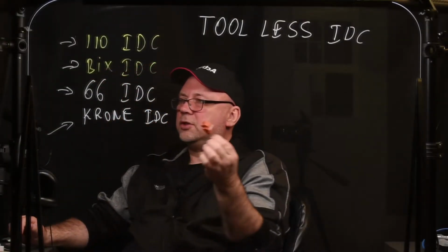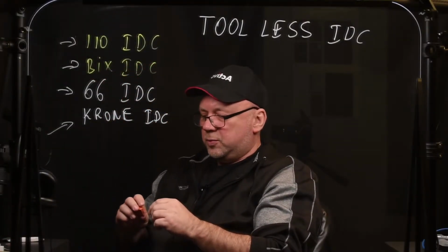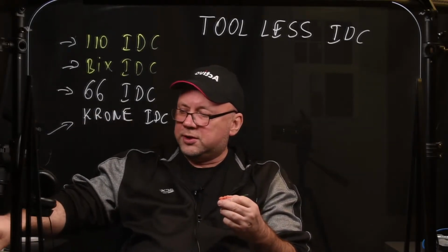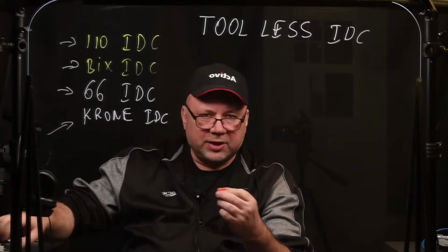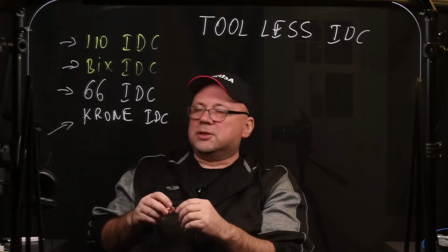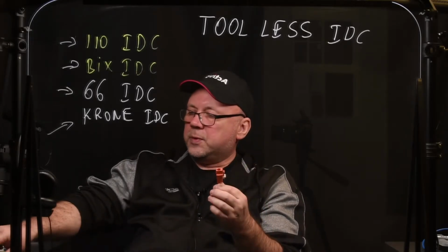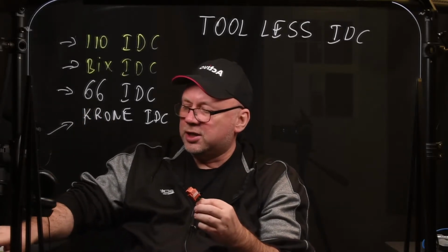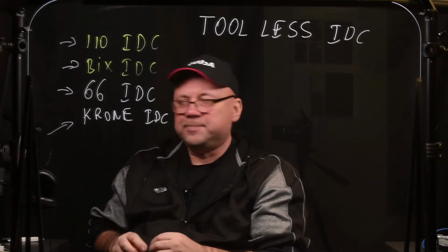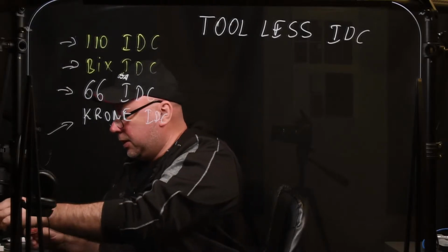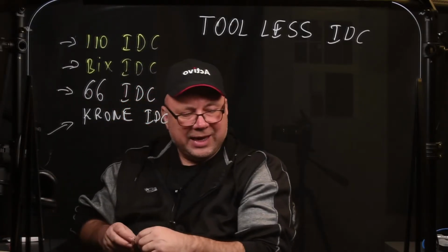All right. So that's the toolless connector. And someone might ask, so why don't we just use toolless so we don't have to buy all those termination punch down tools? Well, in some cases you're going to be dealing with toolless jacks. In some cases you're going to be dealing with connections that involve punch down tools. And my job is to show you as many of them as I can. All right. So now let's get to doing the lab, actually.